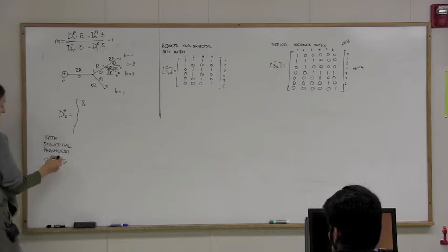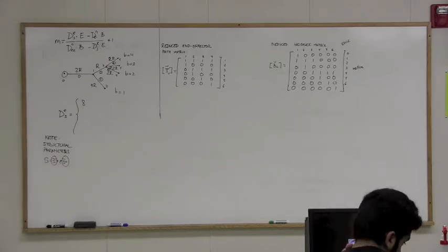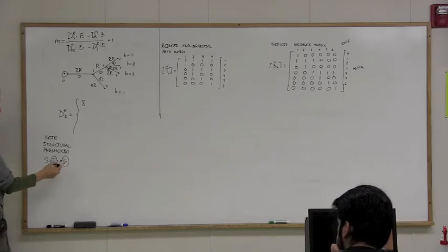These are our unknowns. These are 2 3D vectors, so they are 6 per joint, but we know this has to be unit, and this times this is 0, so there are only 4 independent ones for each joint.